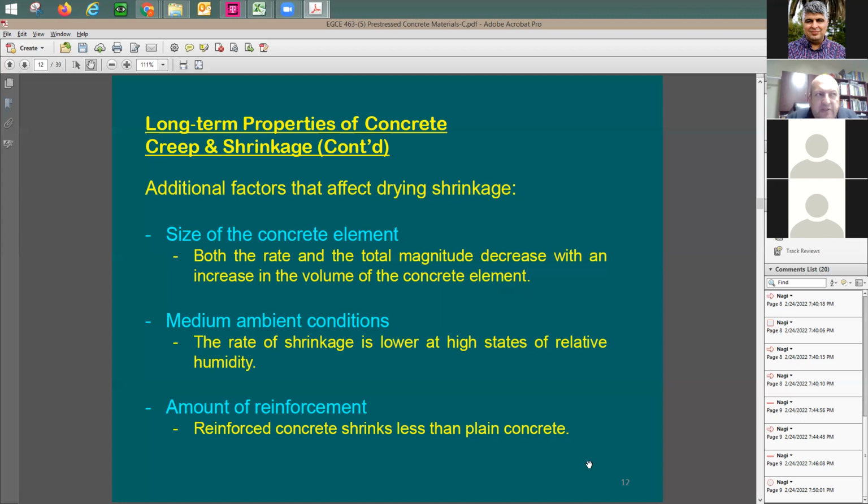Some people would do pre-stressed members and they put more reinforcement at home. Like in some precasters, they don't put any reinforcement. So what do you expect? Yeah, it's true, it's going to be cheaper because you don't put this non-pre-stressed rebar, the conventional rebars, but it means that you're going to have more shrinkage. Once you have more shrinkage, it means more losses when it comes to the pre-stressing. So there's the balance. You need to figure it out.